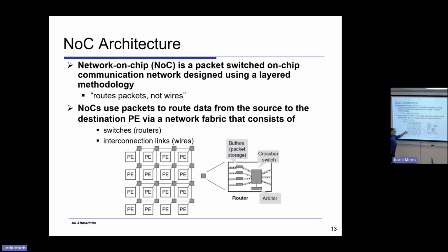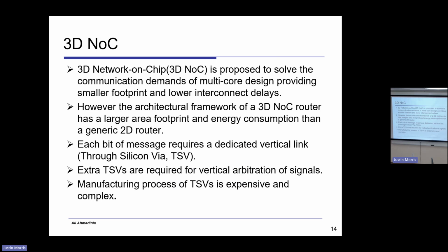So a typical way it has been mostly implemented is using a network. So a network on chip is a two-dimensional network, and we have routers that help us to communicate with the network and send information between these processing elements. Next slide. And then because it was again taking a huge overhead in the system and had a huge footprint, the idea of having a multiple layer chip was emerging. It was about 10 years ago. And then we came with the idea of the 3D network on chip, and many people work on that area. But again, the 3D network on chip has also its own issues.